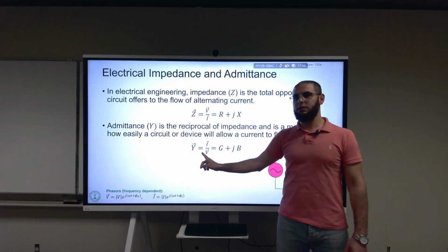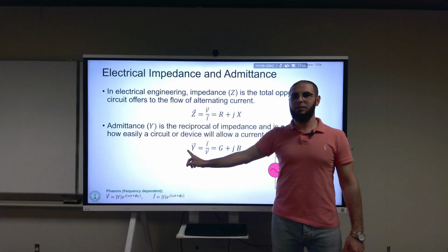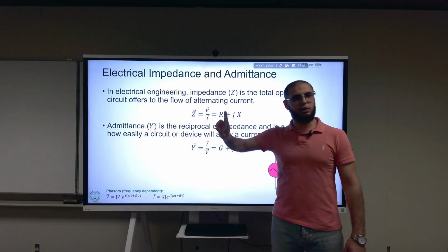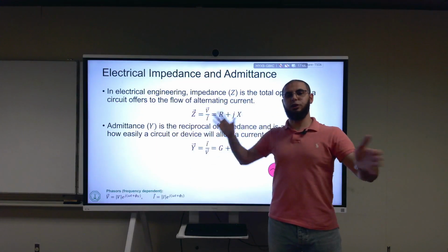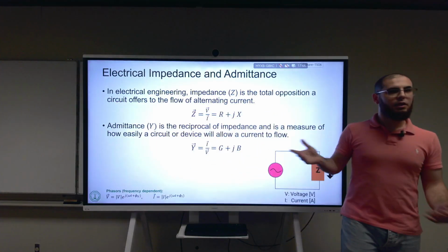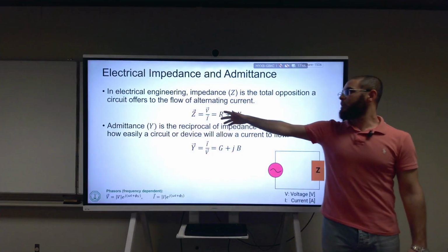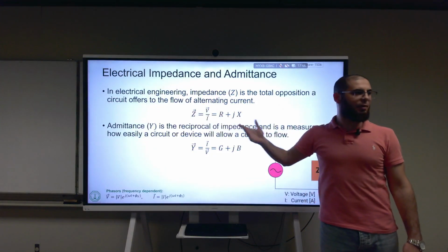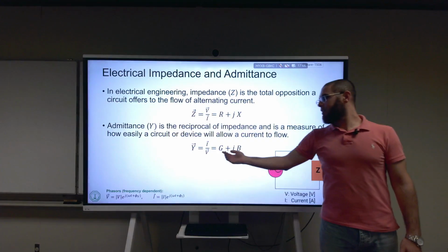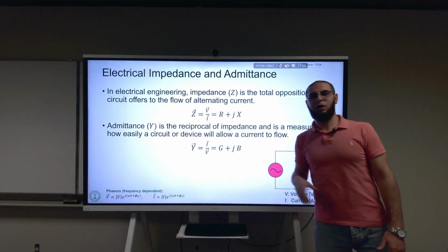And in this equation, I is equal to voltage multiplied by Y. So it's like one has an input-output relation, and this has an output-input relation. It's just the opposite. So we have to look at causality. Here, current is an input and voltage is an output when we talk about impedance, and voltage is an input and current is an output when we talk about admittance.